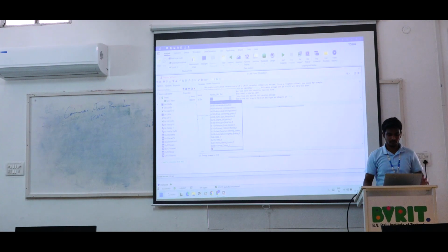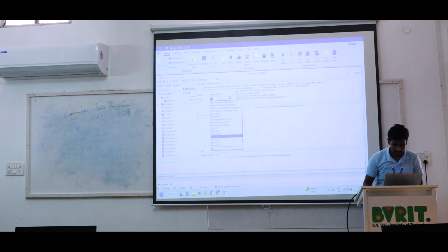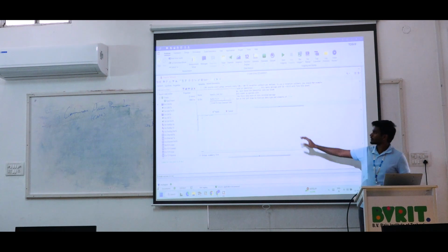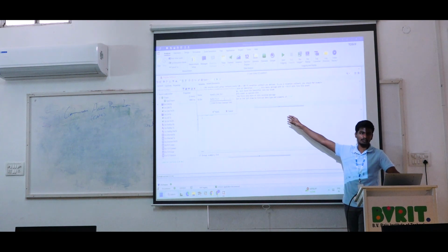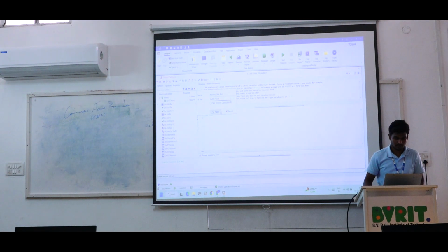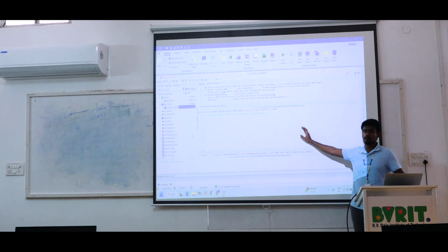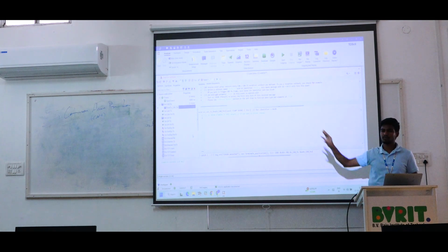Or else, if we are focusing particularly on the TCU, you just select the TCU message one, which means ID number 20. Second last, you just scroll to the last item, you have the TCU ID number 0x20. You just select it. After selection, it is showing the 0x20 and the message name, correct? Okay, and then give apply. So now I am focusing this script on only receiving ID number 20. So we are going to work with ID number 20.